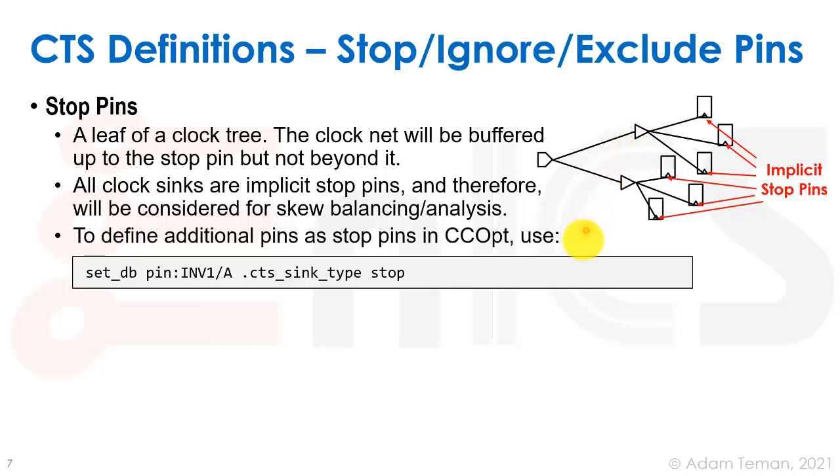Actually, the clock network is one of the most important things at the architectural level in a chip when you're going from the design of the chip to physical implementation. It gets complicated and it's very, very particular per each chip and each macro. One of the things that I always tell the backend guys to do is first things first, bring a picture of the clock tree, a nice schematic block diagram of what you have on the clock tree. You have to look at it, understand what you want to skew balance, what you don't want to skew balance. Are there any things that you want to ignore, or so forth and so on?